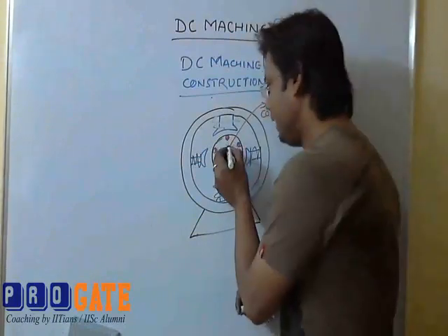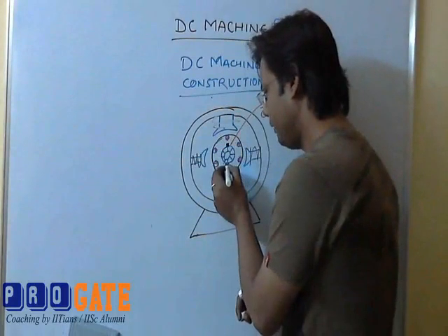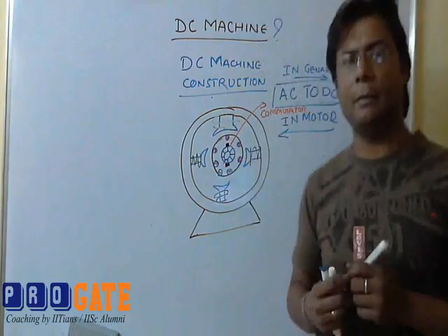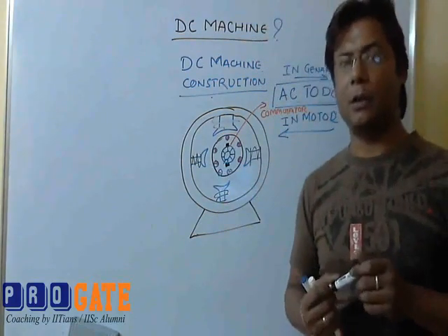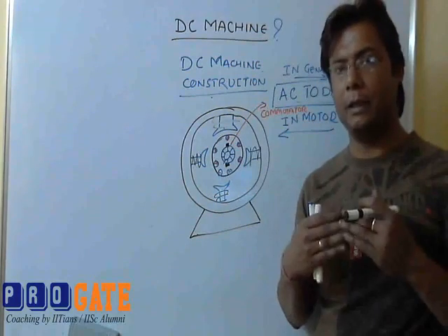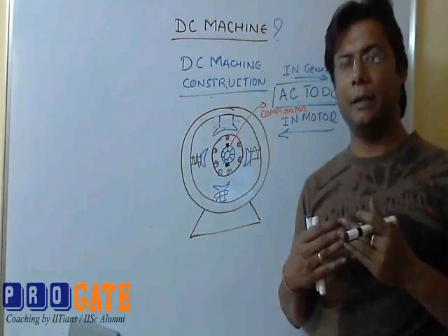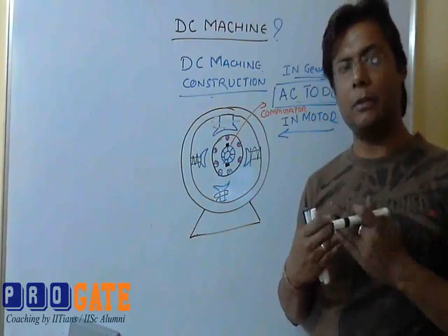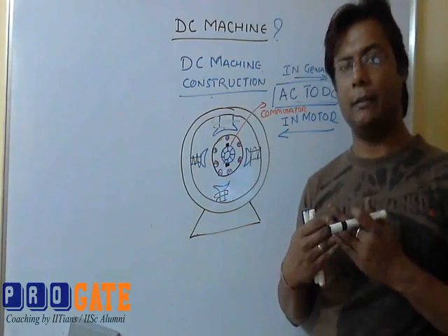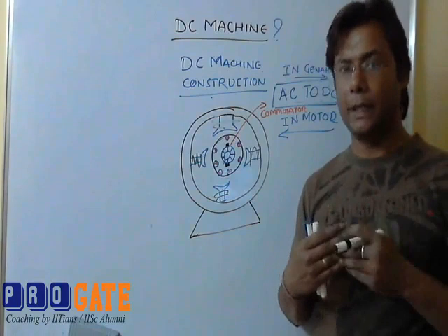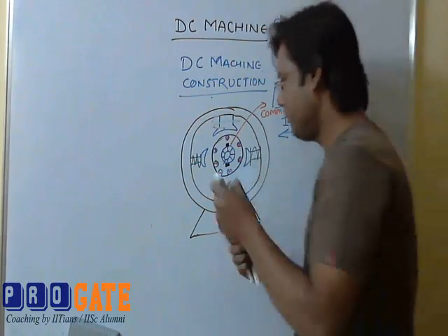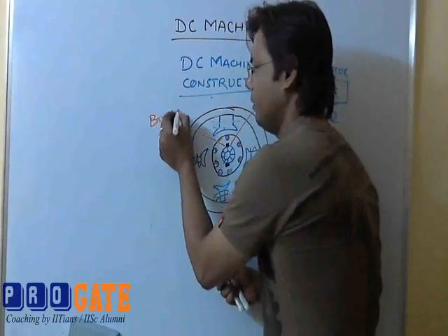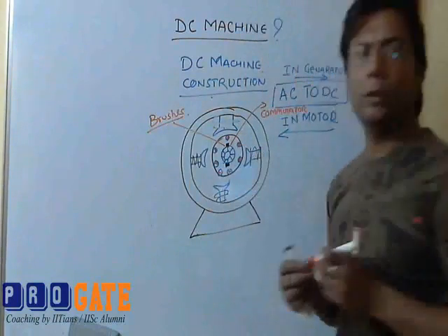Now coming to another thing which is mounted on the commutator, shown in black right now. From these, the wirings will be coming out of the machine. These are called the brushes, which are touching the commutator, and they are held by a spring, so that there is not a harsh touch on the commutator. They are just placed on the commutator so that they can collect current from, or give current to, the machine. Both are called brushes.